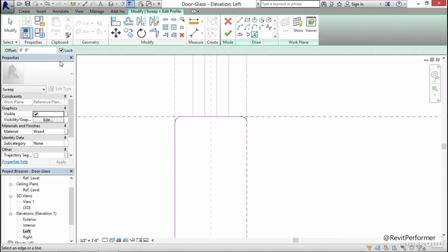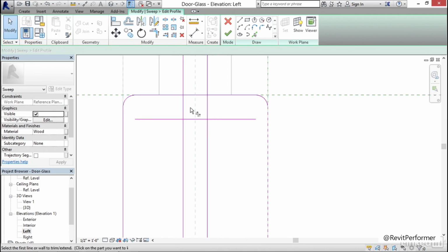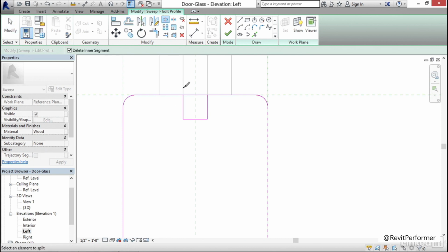Okay, I come in here. My drop panel, pick lines. Offset wants to be 1/8 of an inch. I'm going to go to the left, to the right. Let's offset 1/4 of an inch down. Now I'm going to trim these up. TR for trim. I'm going to click Trim Extend Multiple Elements. I select my reference plane, click here, then here. Hit Escape. Type SL for split.